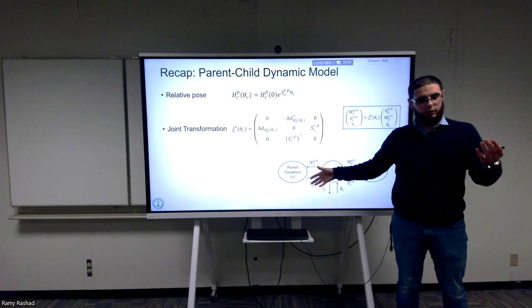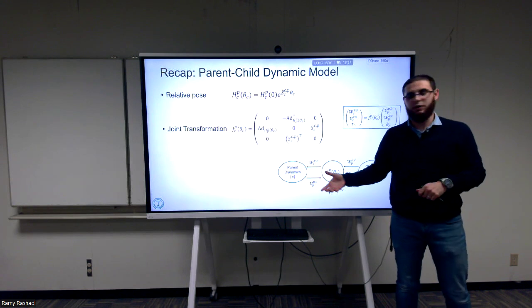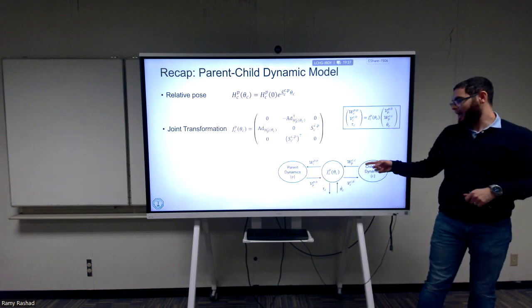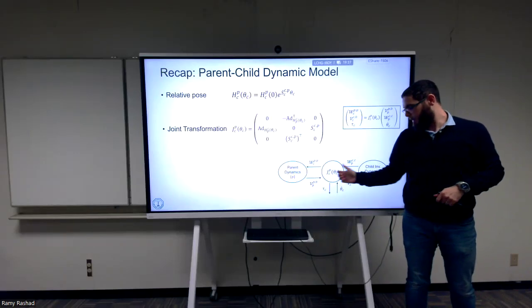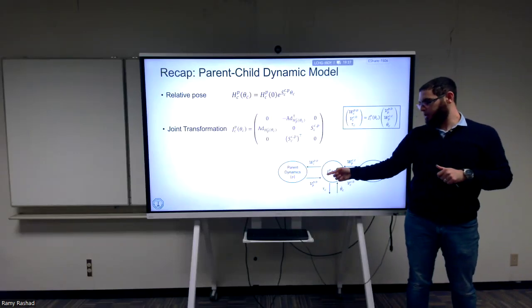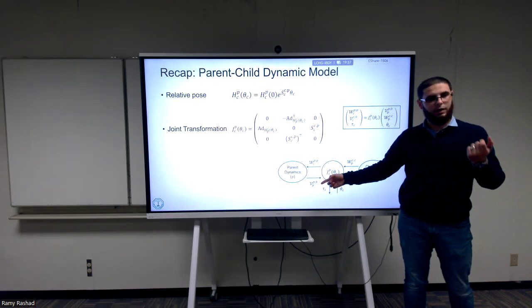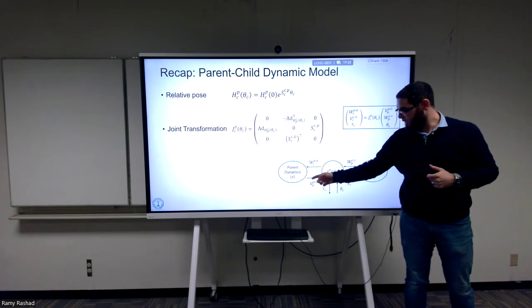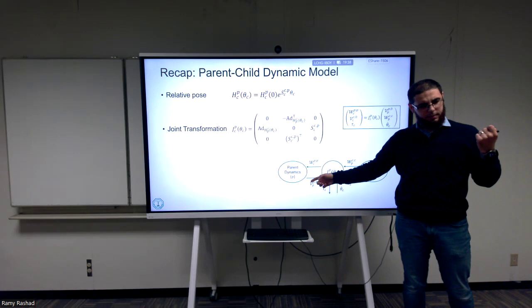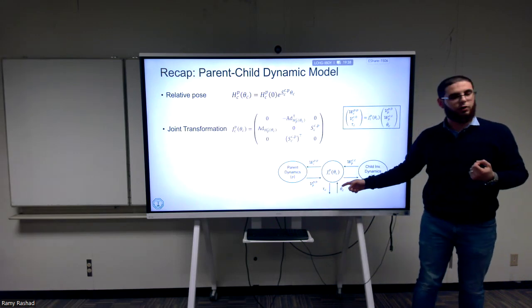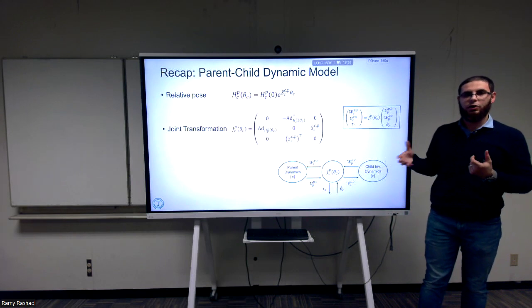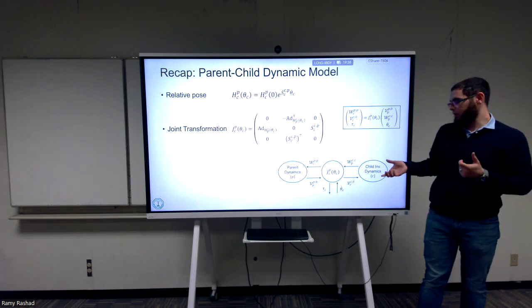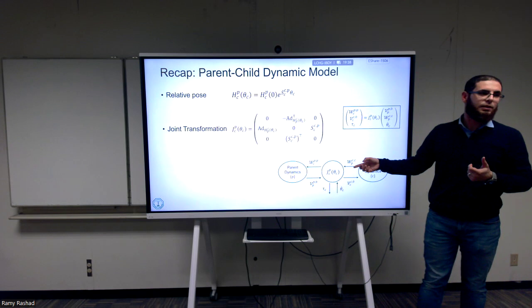So we calculate V dot and then we integrate it, we get V. But in this case, the V of the child is specified or identified with the twist of the parent and the angular velocity of the joint. And in the end, the child dynamics are an inverse causality or a differential causality. And as an output, we get from it the wrench, okay?